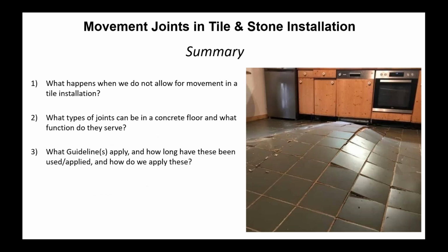All right, let's talk a little bit about some of the things we covered. I think we covered a lot. What happens when we don't allow for a movement joint in tile installation? In most cases, lack of room for movement tends to create tenting or disbonded tiles.